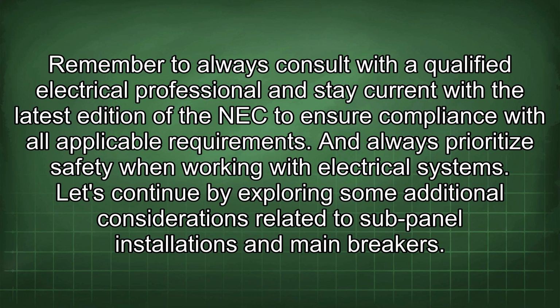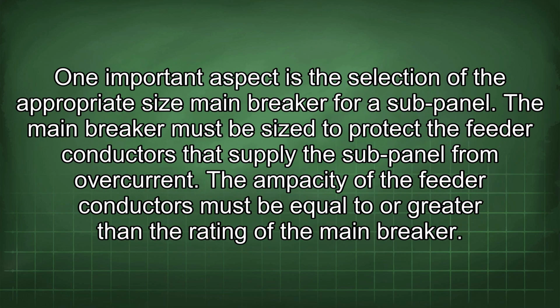Let's continue by exploring some additional considerations related to sub-panel installations and main breakers. One important aspect is the selection of the appropriate size main breaker for a sub-panel. The main breaker must be sized to protect the feeder conductors that supply the sub-panel from overcurrent.